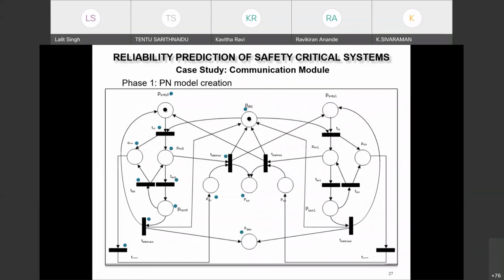And now, for this algorithm, let us try to construct a Petri net model. So this is a Petri net model. Let me explain each of the places and transitions. Again, all the transitions have weight 1. The place PSRDY, if there is a token in this place, represents that the embedded unit is ready to send the packet with semaphore variable equal to 0. And I have initially put one token at one more place, known as PDSR, which represents that the embedded unit gets the request from the display unit to send the data.